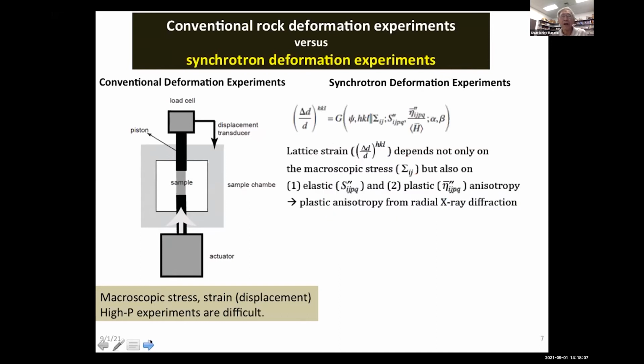And theory was developed in 2009. I wrote a paper on it, how you estimate stress from the diffracted X-ray as a function of various orientations. And the main conclusion is diffracted X-ray shows the deformation of lattice spacing depends on the angle at which diffracted X-ray is collected. And therefore, the displacement depends on the angle, and from which you can determine essentially strain along certain directions.